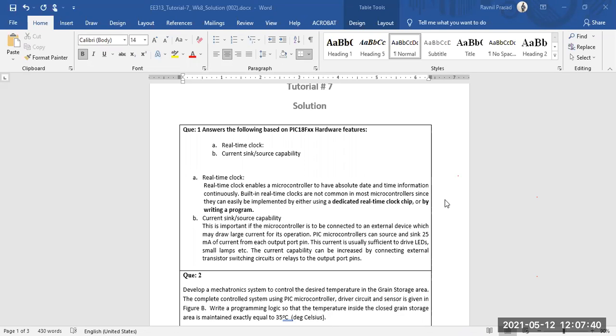There are other instances when we are using other devices or controlling other peripherals, where some sort of current is given back to the microcontroller. Basically, that is the sink current. So current sink is the ability of the microcontroller to withstand a certain amount of current, while for current source capability, the term itself defines it. Basically, we are sourcing current. We are giving out current.